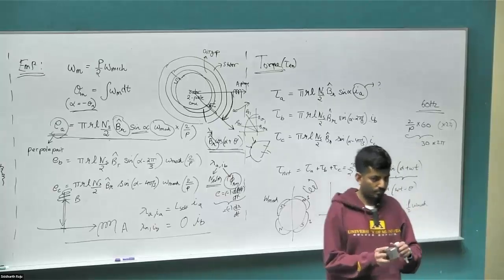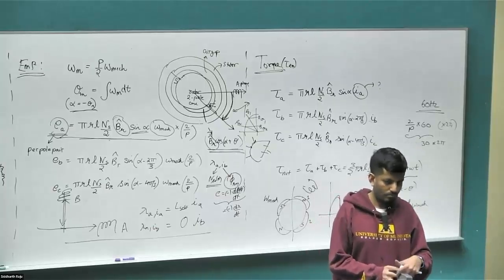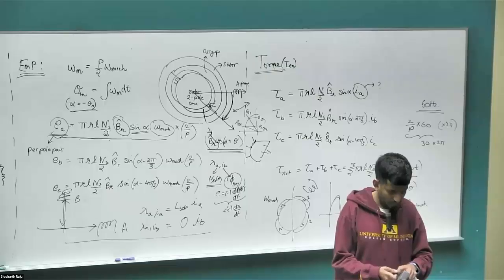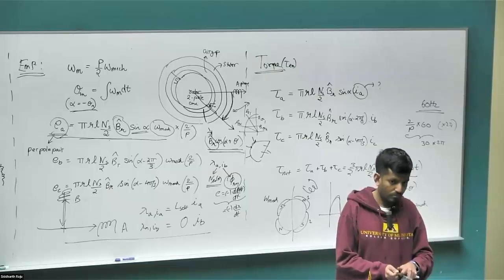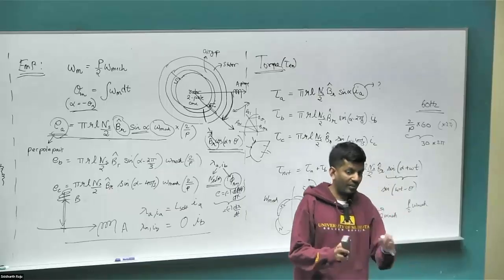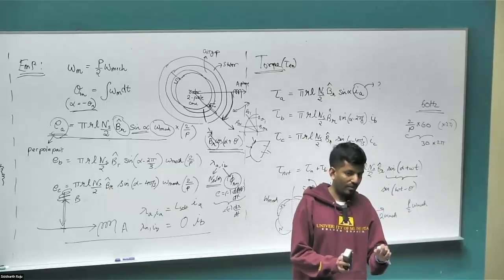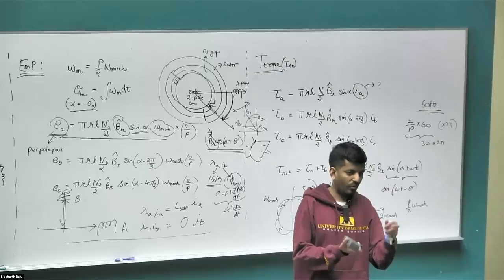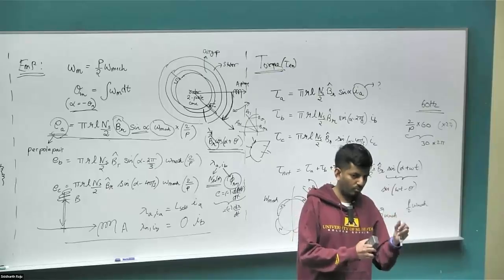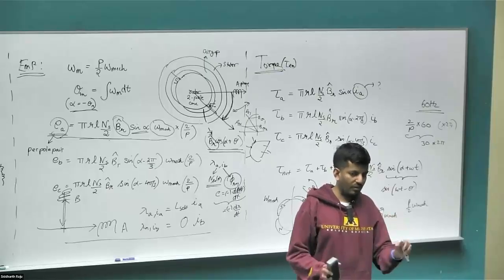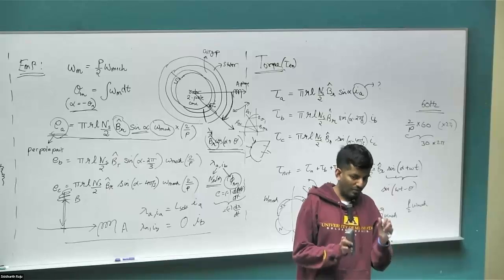For the homework questions, when it says 6-pole 3-phase, does that mean that there are 3 phases per pole pair? The phase is independent of the poles. Right? The motor is either a three-phase motor or a two-phase motor. The homework I've given has both three-phase and two-phase considerations. The phase is completely independent of the poles. You can have a three-phase motor.